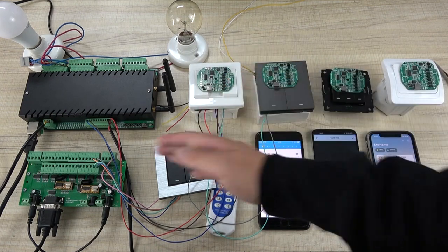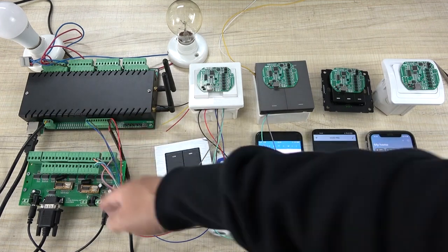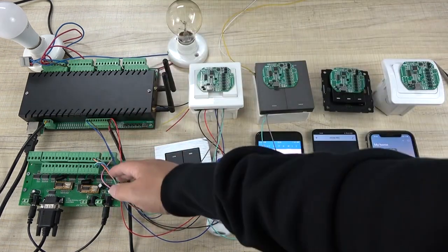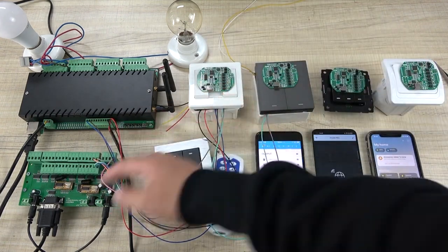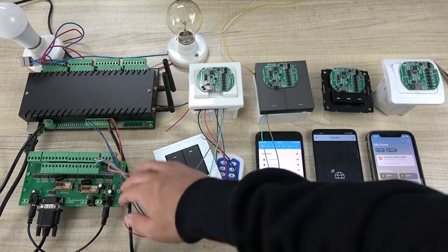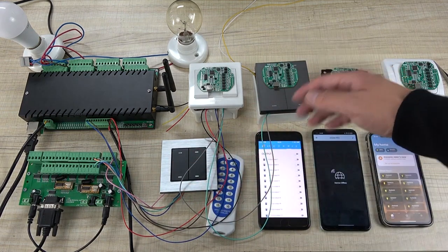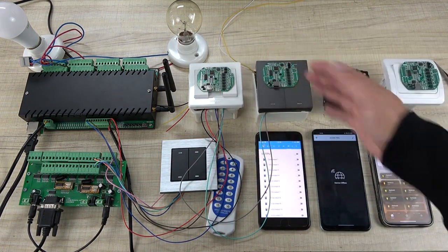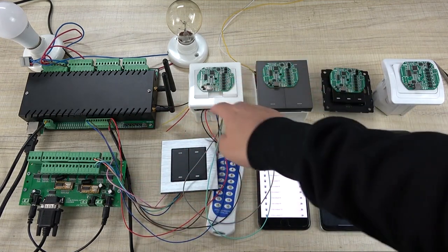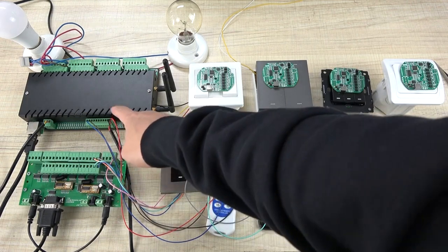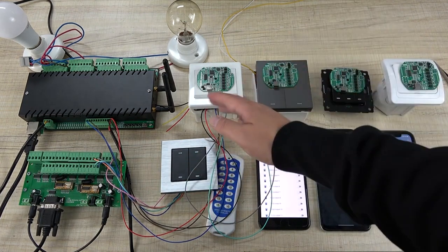And if you use the other way, you can just choose any dry contact. So there are so many cables, but that will be very stable because there is no software and no communication, just an on and off switch connected directly. And in some projects and situations, you can't use so many LAN cables. So for some switches, you can use this RS485 solution and connect to this controller. So just two wires, and that will be easy to place a new one.